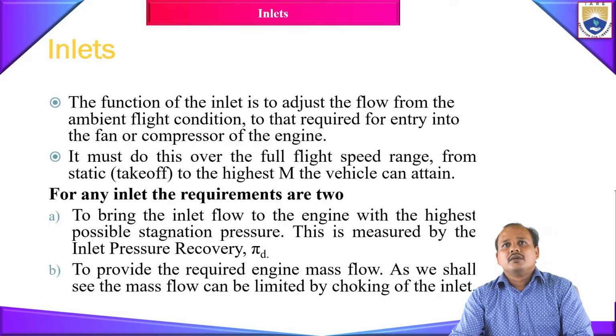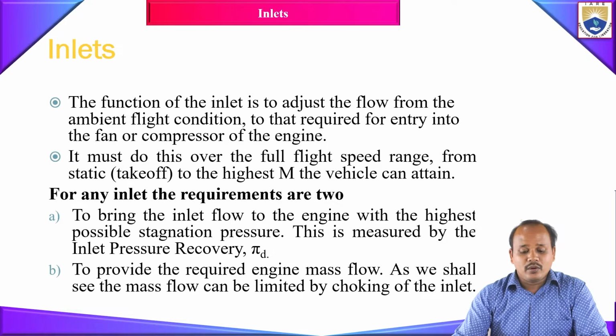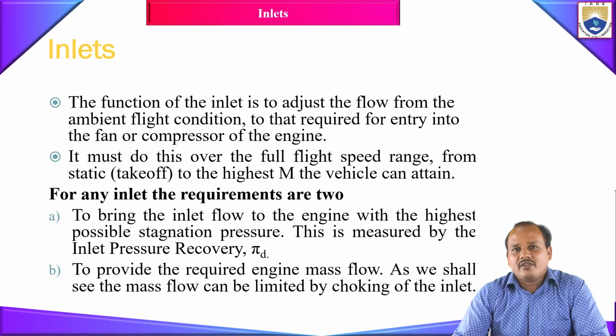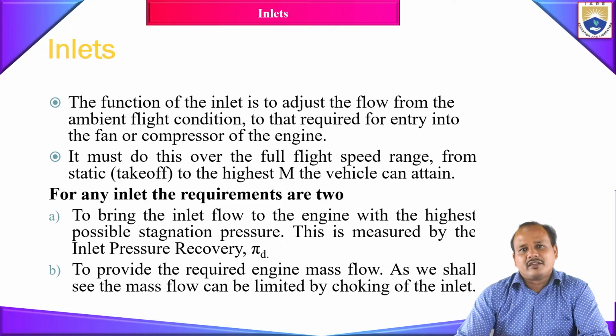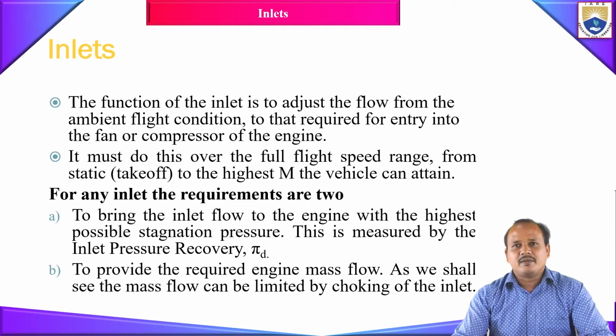So let's start with the intake. What is the function of your intake? Basically, the purpose of your intake is to supply the required amount of mass flow rate to your engine irrespective of the operating condition. What is the meaning of operating condition, or to be precise, flight envelope? For example, if a gas turbine is fitted within an aircraft, during your start, that is on the ground, your aircraft is still, and during that time also the intake has to supply sufficient mass flow rate to your engine.